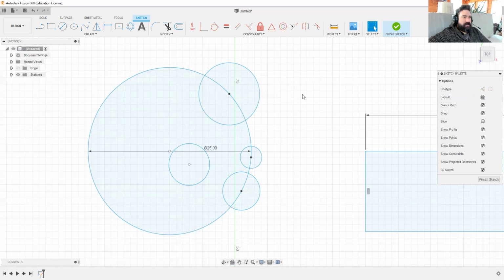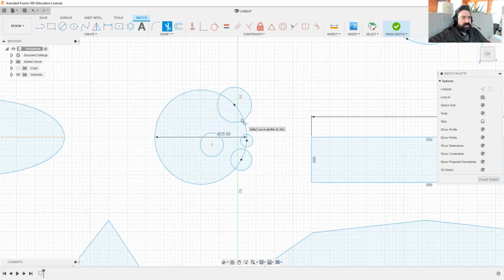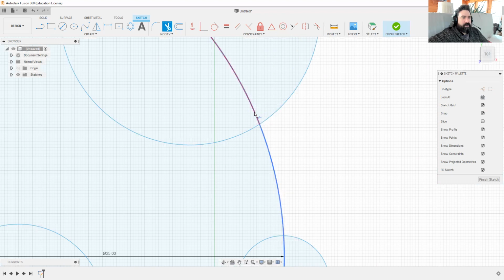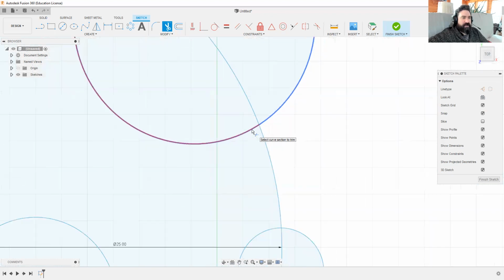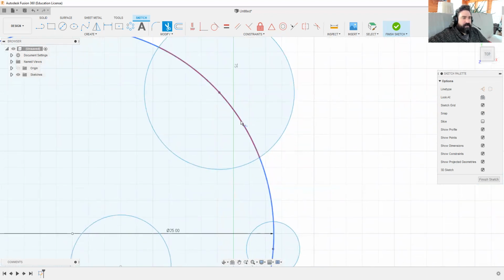But one of the things we didn't talk about last night is some of these modifier tools, mainly things like trim. Well, what if I don't want to have to select things like this, or I want to actually remove parts? Well, the trim is how you do that, and that's the same with any other program. Trim. Press T if you like for a hotkey, but now I can chop sections out based on line segments. You see, as I mouse in here, it will highlight the section that I'm mousing over, the blue line, with red, and that shows you it's planning on trimming that out. So now I can say, let me chop that out.